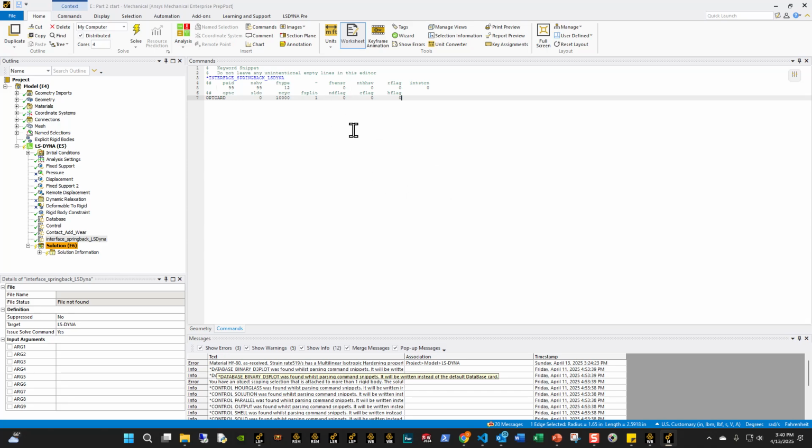And that's what you saw earlier in that video: based on 10,000 cycles, I can look at how much nodal movement I have in that contact interface. Now I can set this number to 5,000 or 1,000 or 100. You're just going to have a different amount of nodal movement, right? This is essentially a multiplier to how much wear depth we have on a single cycle. We're just going to multiply the single cycle value by this number to get a total estimation of 10,000, 5,000, 1,000 cycles of wear, right? So this number is very critical. Of course, I want to set my FS split to 1 to give me my Dyna geo file.